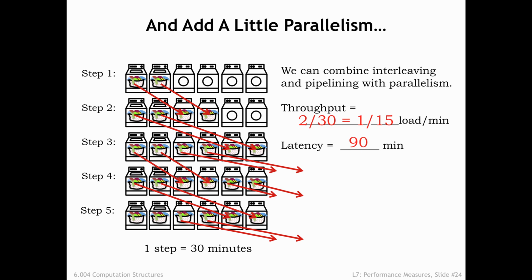We've seen that even with slow components, we can use interleaving and parallelism to continue to increase throughput. Is there an upper bound on the throughput we can achieve? Yes. The timing overhead of the pipeline registers and interleaving components will set a lower bound on the achievable clock period, thus setting an upper bound on the achievable throughput. Sorry, no infinite speed up is possible in the real world.